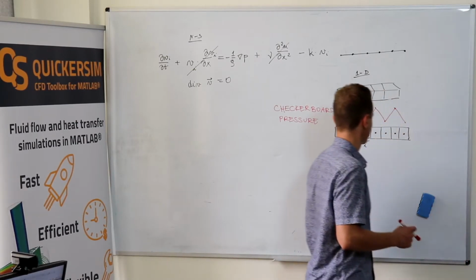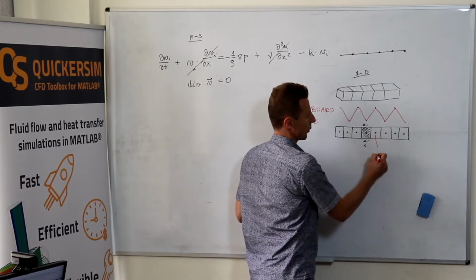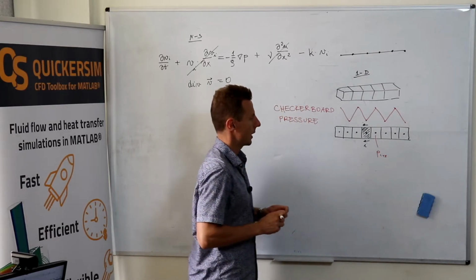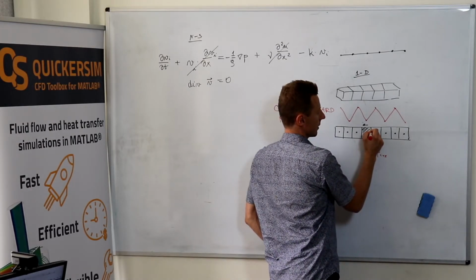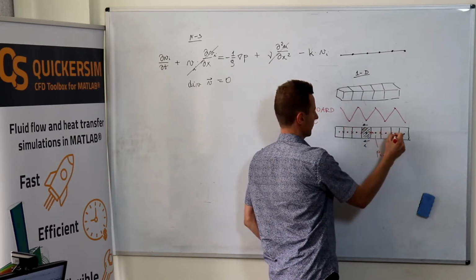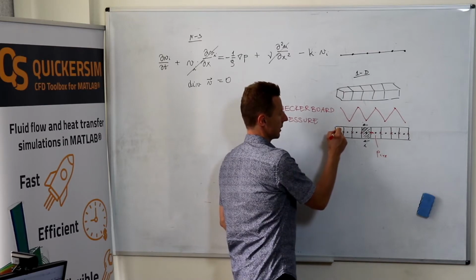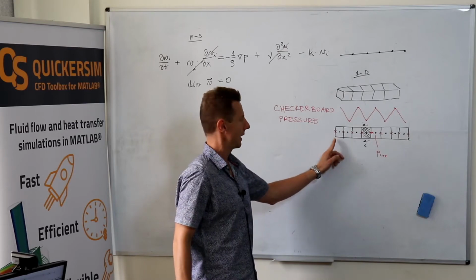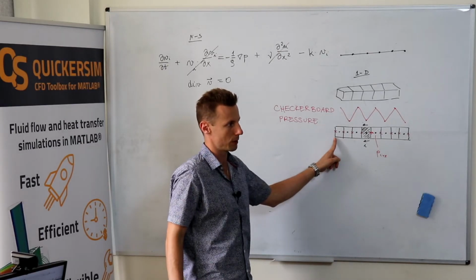Typically we are saying that we will store pressures here at the centroids, but what we would do is transfer the point where we are storing the velocity variables to the interfaces. Then it turns out that if you want the inflow boundary condition, you already have some velocity value exactly at the inlet, which is nice for implementation of the inflow boundary condition.